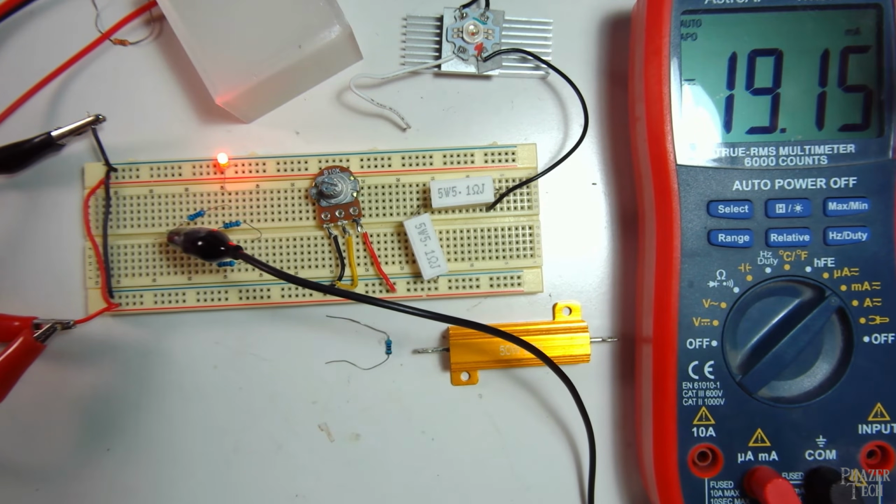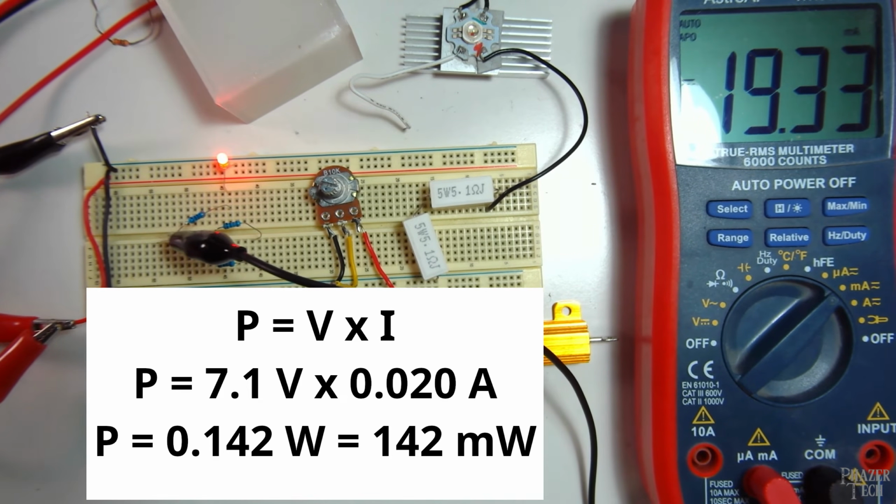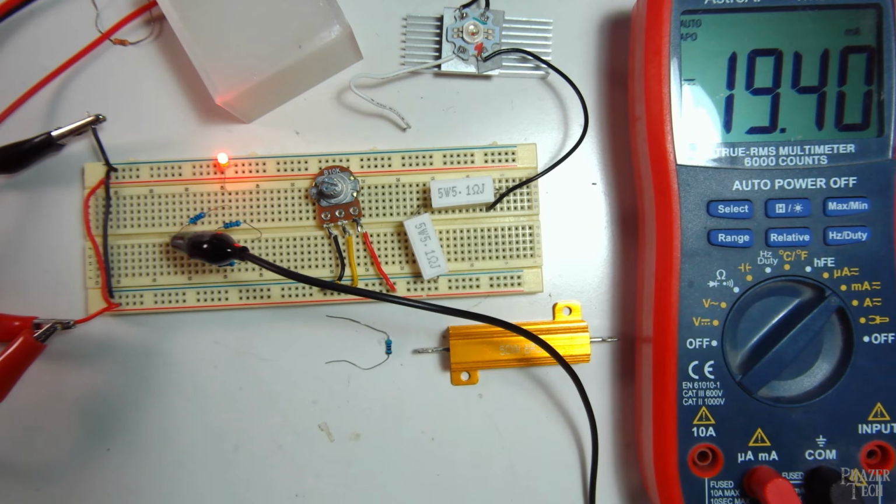So yeah, you can see 19 milliamps, which is really close to 20. So anyway, back to power. To figure out how many watts the resistor is consuming, all we need to do is multiply the amount of current that's flowing through it times the voltage drop across it. In this case, it's 7.1 volts times about 20 milliamps equals 0.142 watts, or 142 milliwatts. Since this is a quarter watt resistor, it can handle that just fine.